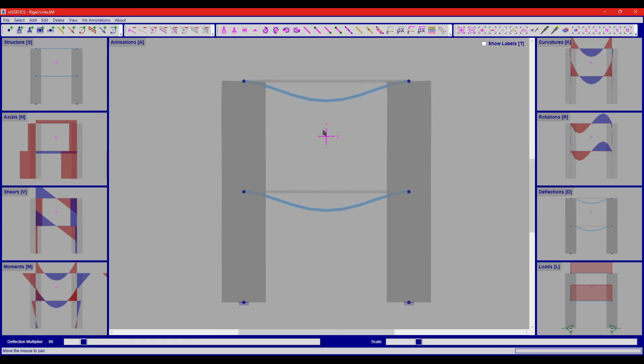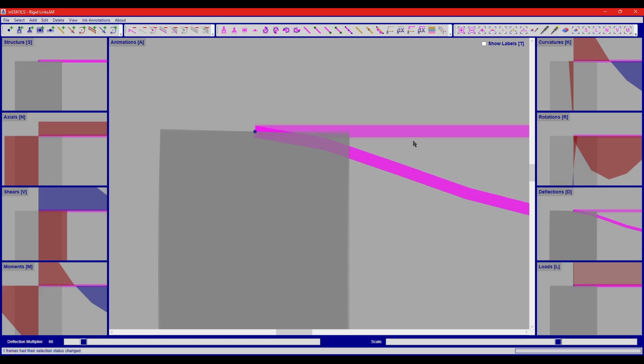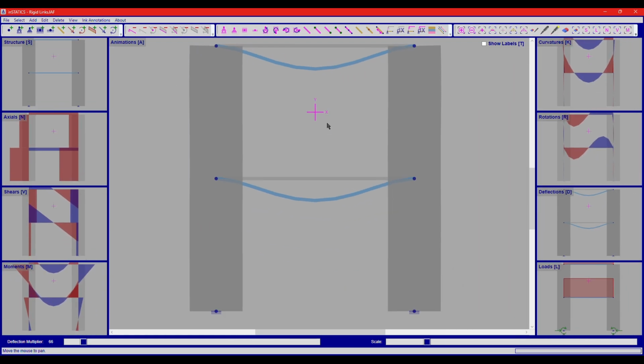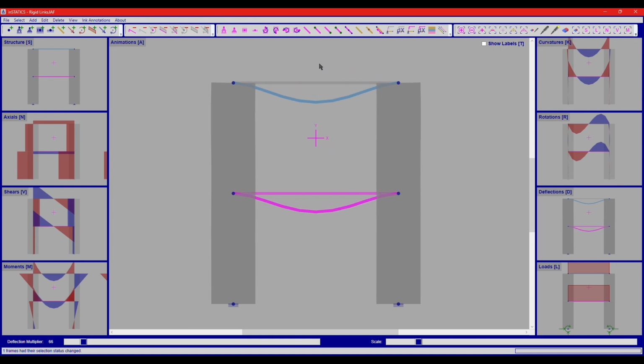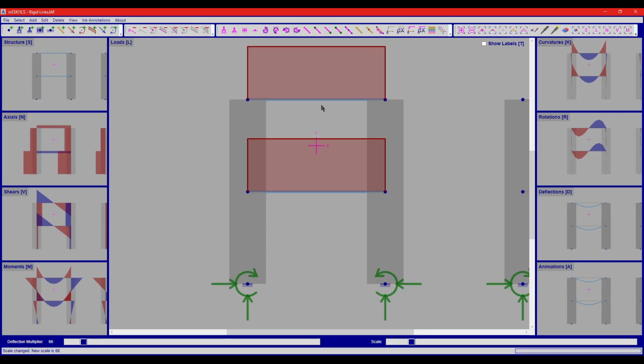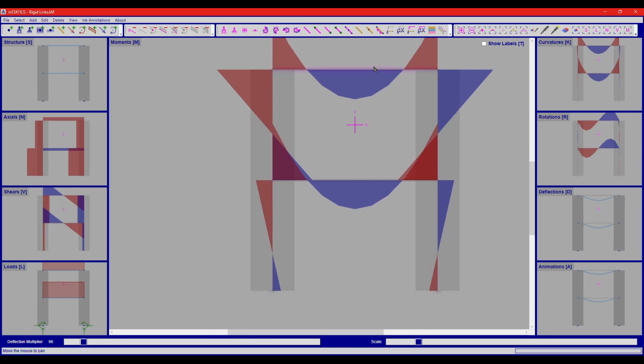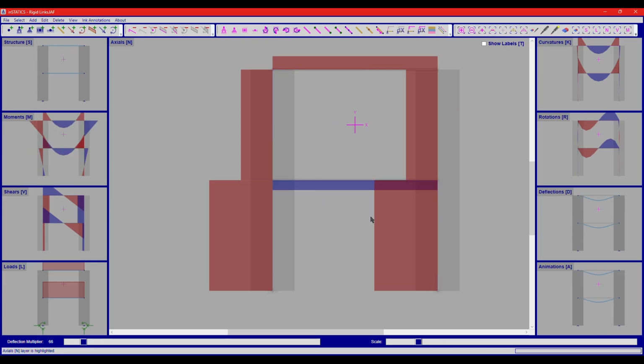When we try the same strategy with deeper frame sections, things start to look a bit strange, especially closer to the joints. It appears that our beam is starting to deflect long before it even exits the column, overestimating the actual length of the beam and its midspan deflection. We're also applying loads over the entire length of the beam, overestimating the actually loaded length. Not to mention, the distribution of the internal forces is not accurate at all because of this unexpected and sometimes unaccounted behavior.